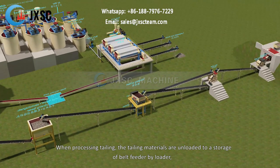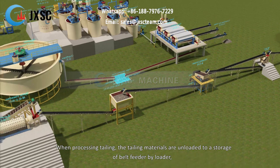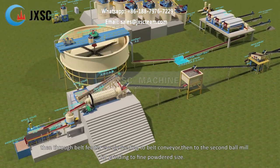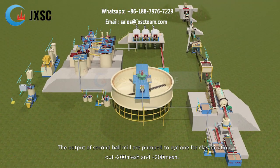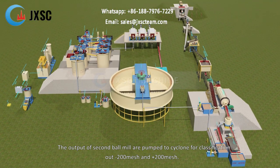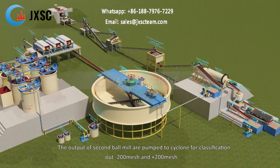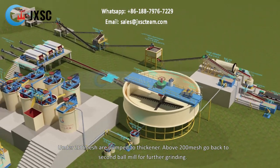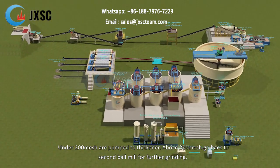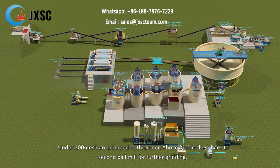When processing tailing, the tailing materials are unloaded to a storage of belt feeder by loader, then through the belt feeder evenly fed to the belt conveyor, then to the second ball mill for grinding to fine powder size. The output of the second ball mill is pumped to a cyclone for classification into smaller than 200 mesh and larger than 200 mesh. Under 200 mesh is pumped to the thickener. Above 200 mesh goes back to the second ball mill for further grinding.